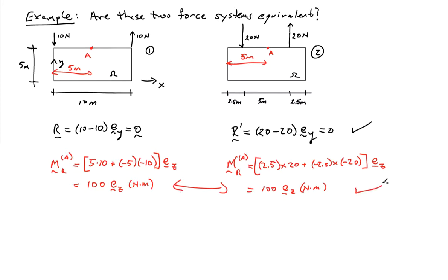We've shown that we have the same resultant force for the two force systems, and we've shown that we have the same resultant moment for the two force systems at one given reference point, and that means it holds for all reference points. So the answer here then is yes, equivalent.